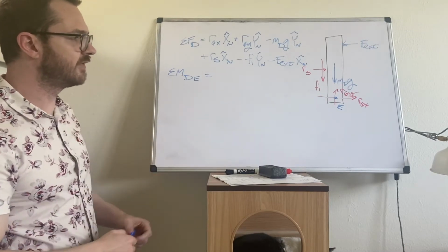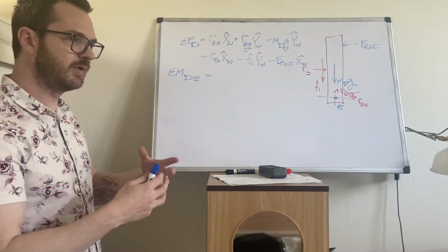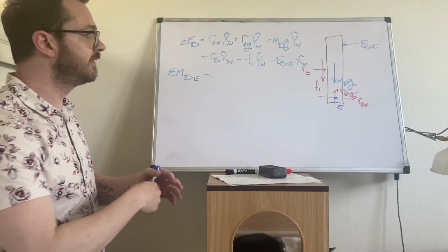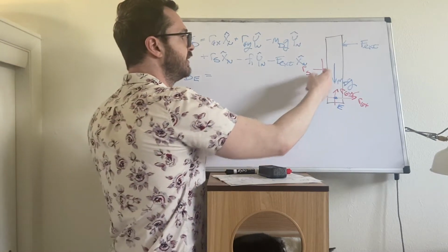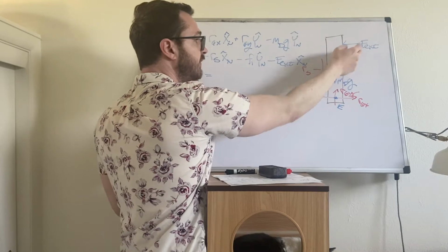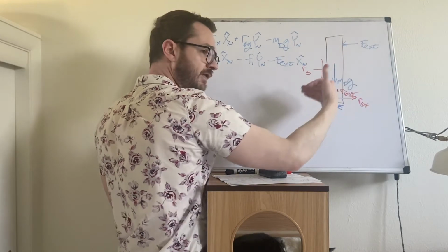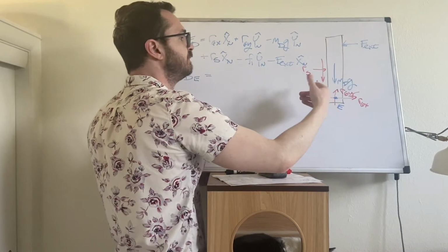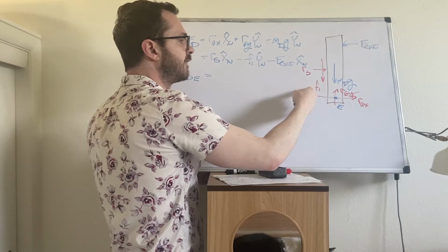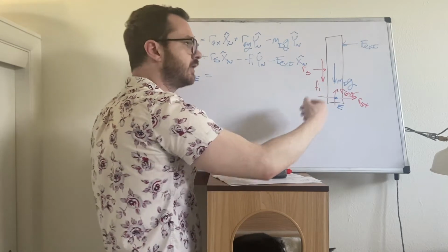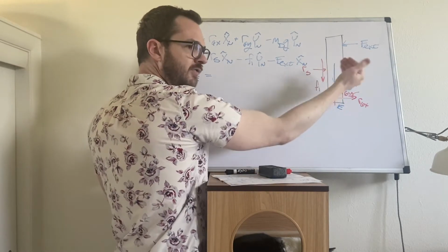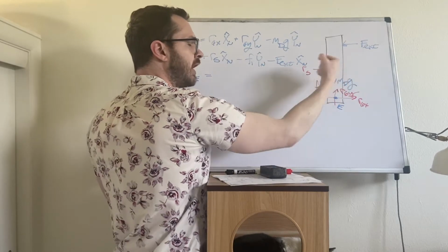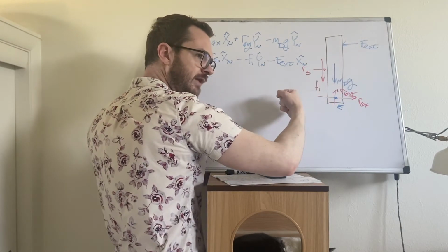We're actually going to see this come out of the math once we're done. But imagine that you're applying a force, right, to create a positive moment, and you're driving the handbrake into the spinning disc. It's possible that the friction could actually contribute. It could actually generate a positive moment as well, and the friction can drive the handbrake also into the disc.